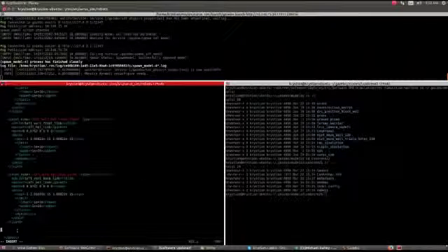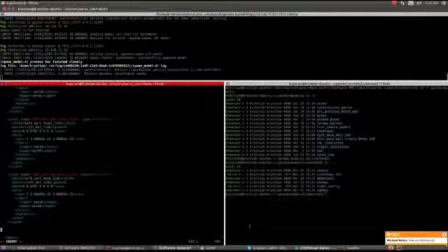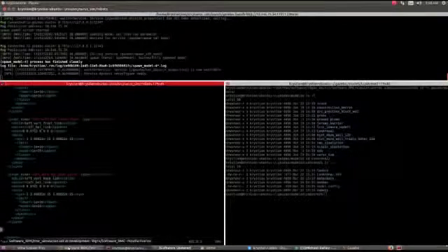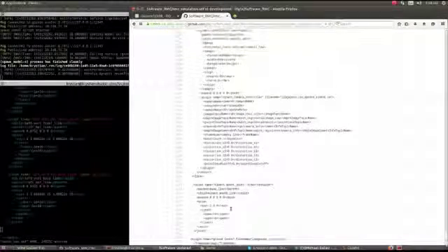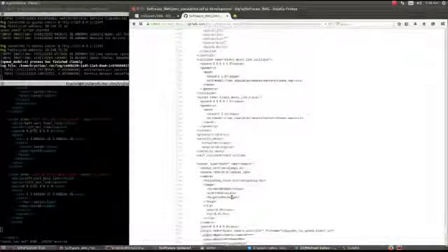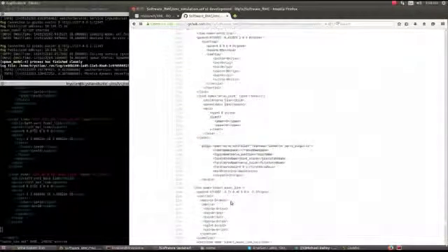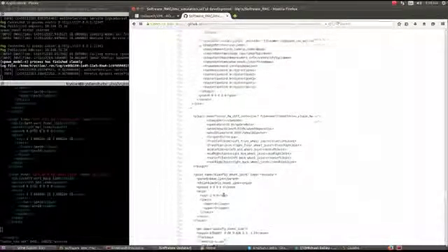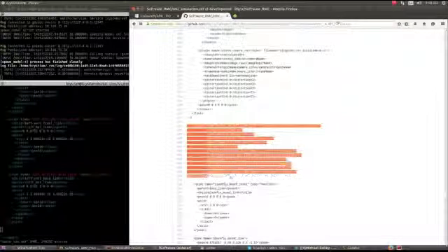So now what we're going to want to do is insert a ROS plugin. I'm just going to reference one of the previous versions of this model that I've used in the past. All this stuff is accessible on the GitHub. You can view the different plugins that I used on my other models as well. But we are interested in the 6-wheel differential drive system. So here, this plugin right here, and this plugin is part of a package that you will need.